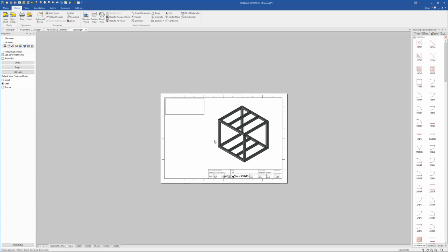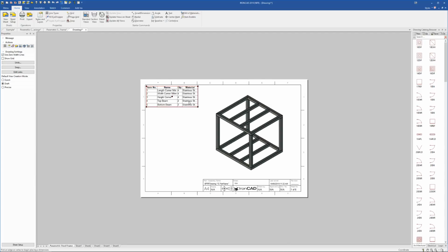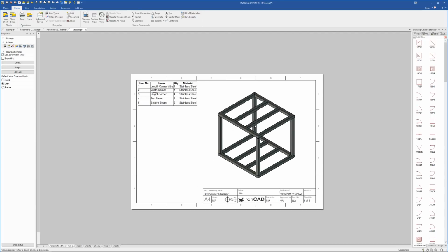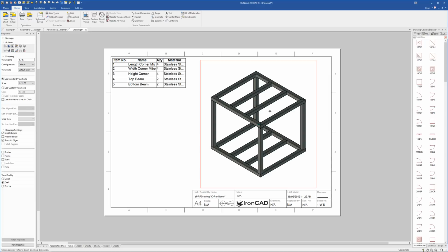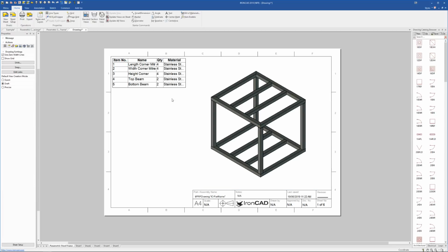You can see if I go over to the steel frame one here, which is the assembly one I used, this one's also bringing in for us the actual isometric view of the whole model and doing a shaded rendering on it. You can also set it up to use sheet metal unfolded view, so automatically place an unfolded view of your sheet metal part alongside the normal view.